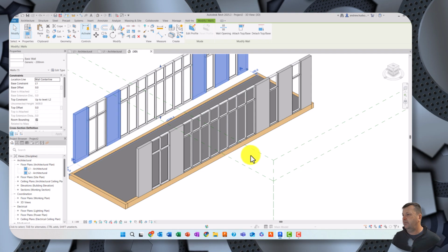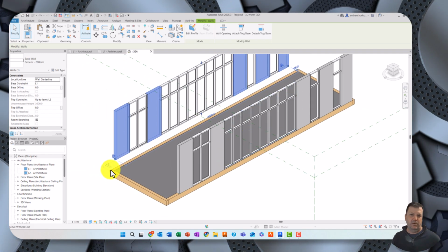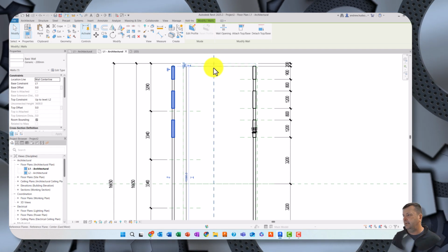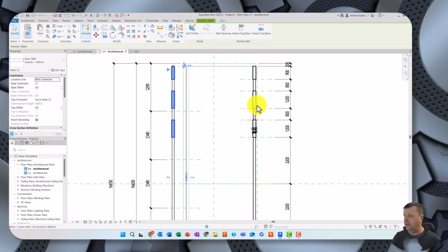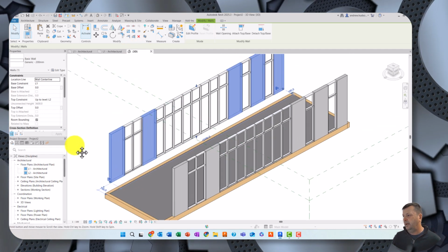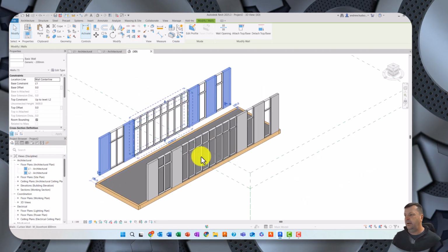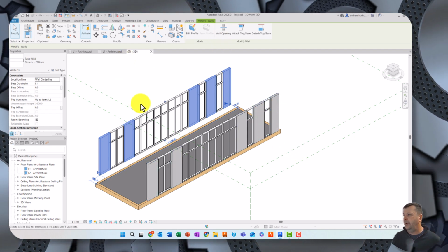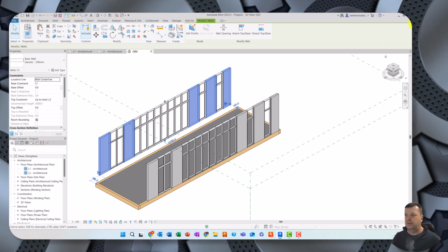If we look at that in the 3D view, you can see that the wall's done on the other side. So if my reference plane here had been centered, which it's not, but if it had, then that would have mirrored around there, and then you would have had the second wall drawn without any issues. And then you're ready to put the columns in on the corners and then the roof. And that's it. That's how you do it all.